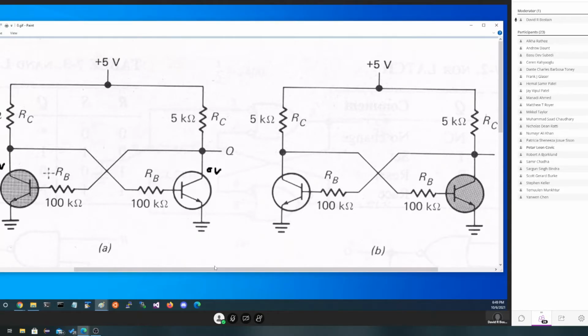He's going to get 0.7 volts right here. When he gets 0.7 volts there, he's going to pull this to ground. And this being ground means this guy's going to have ground here, which supports the idea that he's off. And if he's off, he's going to have basically 5 volts here, which we'll call a 1 in the future.